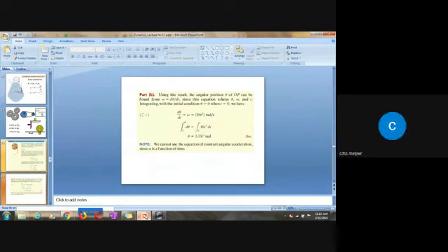No, we use the dot product if you are interested only in magnitude. And if the output required is in vector form, then you will take the cross product. If you recall, we did the same in the case of moment, and if you recall your previous lecture, at the start, we explained this. It is v equal to omega cross r, not r cross omega.